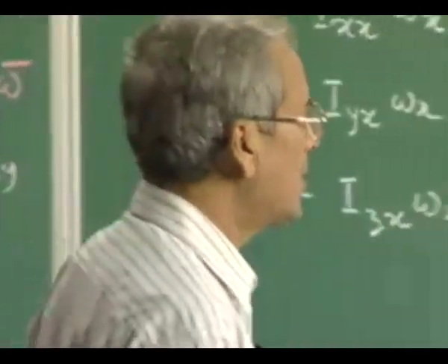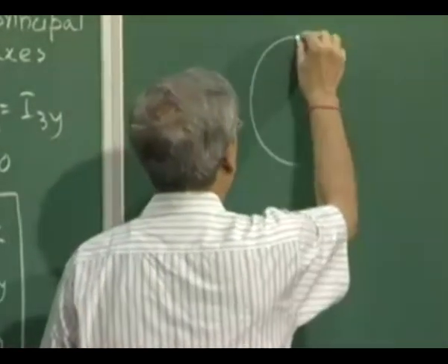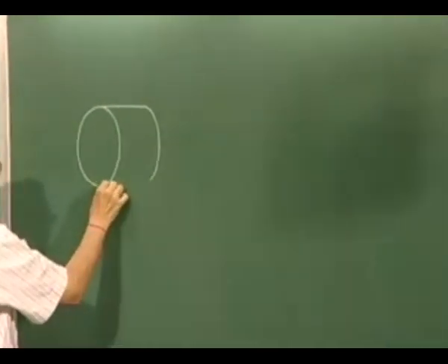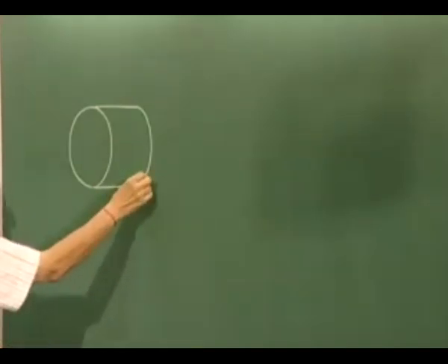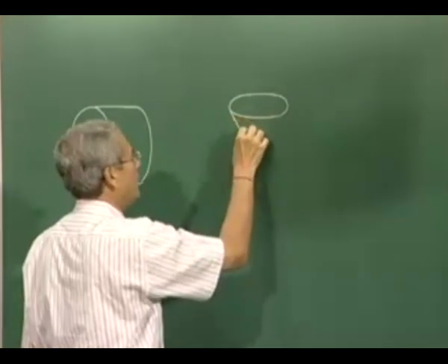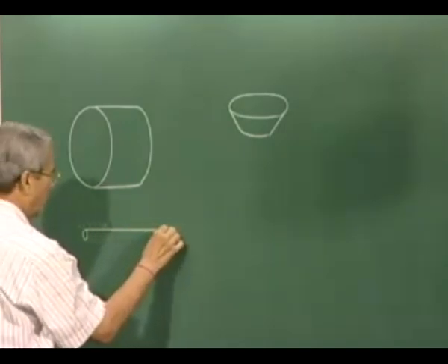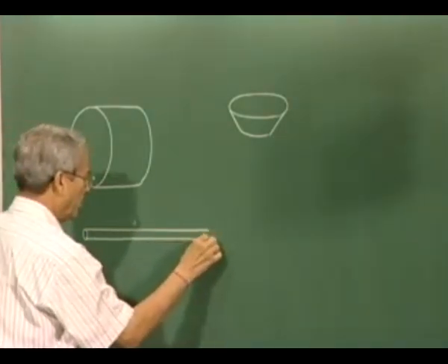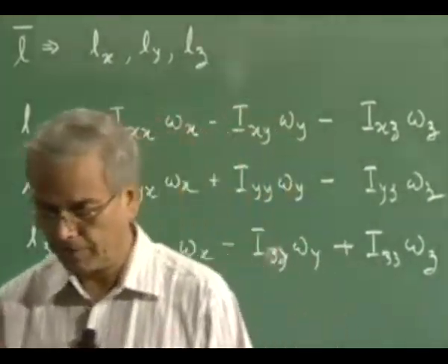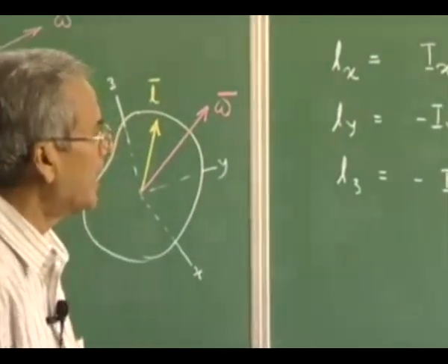In most engineering applications objects will have certain symmetry, like for example a roller or a disc, a gear, a clutch plate, all such things, or simple rod-like objects. In most cases, these are the kinds of component shapes we will be dealing with. And for such cases, it is easy to determine the principal axis by observation.